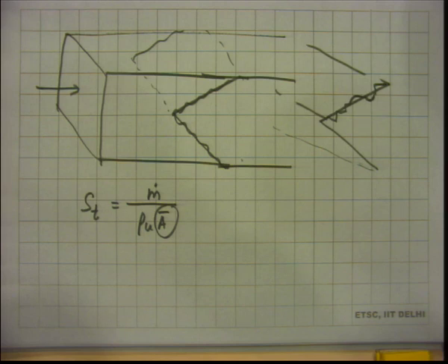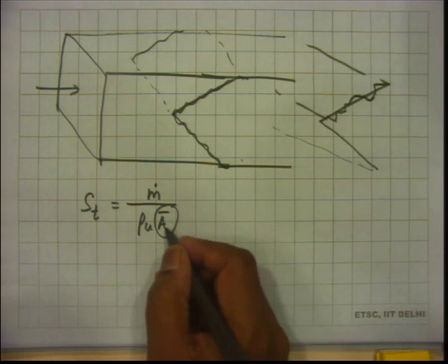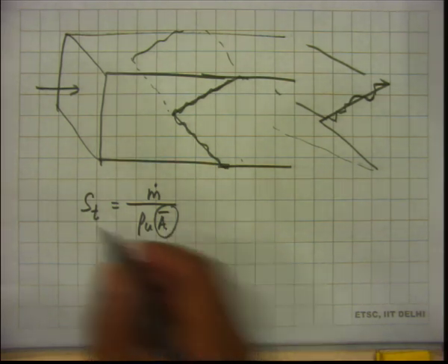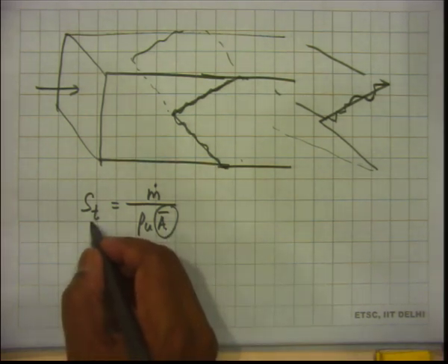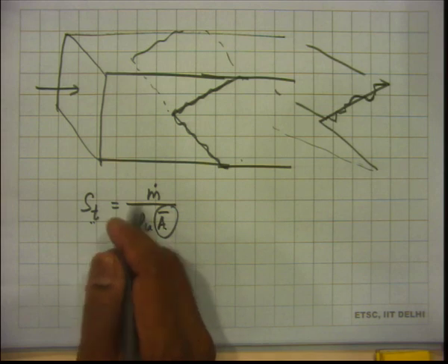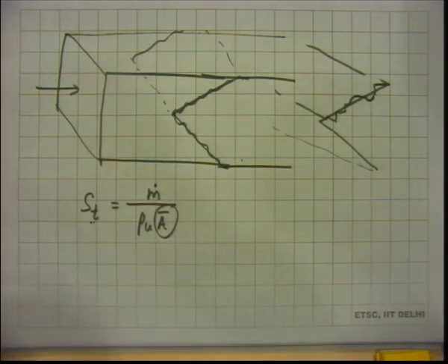The turbulent burning velocity, because to get the turbulent burning velocity you are using the smooth time averaged area, which is actually smaller, right. So this will give you a higher value of turbulent burning velocity than the laminar burning velocity. So we do not want to use A flamelets and SL, because that is a hard thing to do. Okay, how do you know A flamelets? Very hard thing to do. So we will use this.